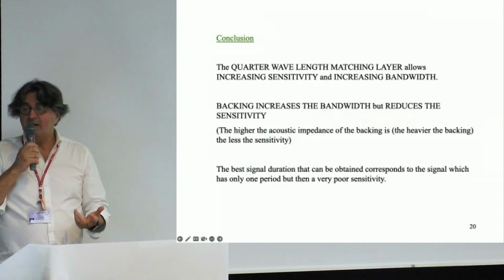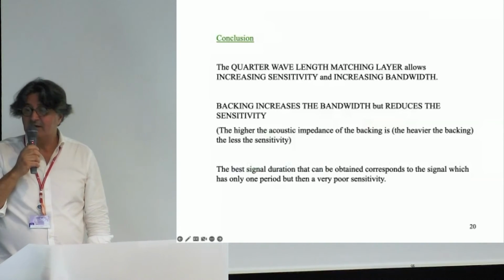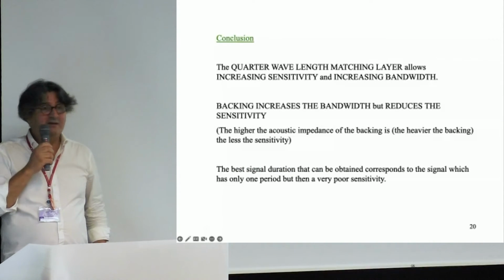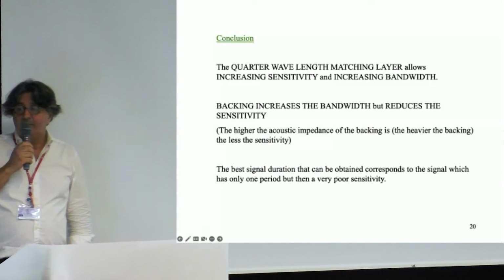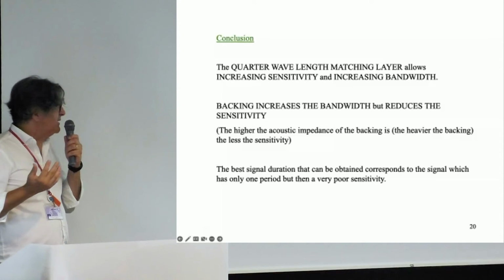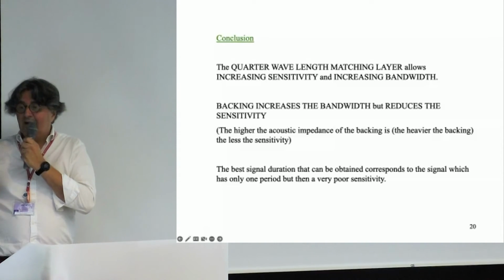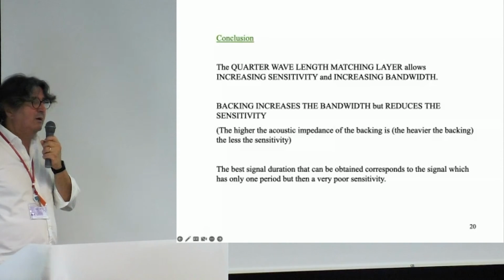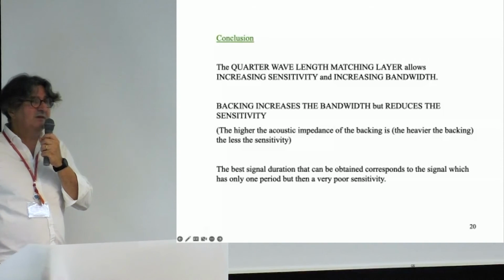The higher the acoustic impedance of the backing is, the less the sensitivity. The best signal that we can obtain is a signal that has only one period, but it has a poor sensitivity.